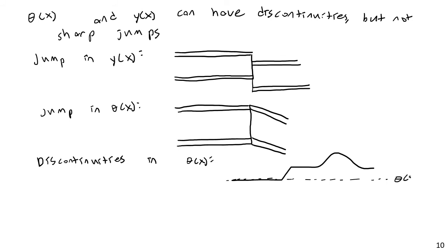Would you draw diagrams for deflection? The question is, would we draw diagrams? Sometimes you can, especially deflection more than the slope. But notice here, we have several discontinuities. We have 1, 2, I guess 3 and 4 discontinuities here. But in each of these cases, even though we have discontinuities, we don't have jumps. Because again, if we're actually going to have a jump in the theta function, our physical beam would look something really weird like this. Same thing with y as a function of x.